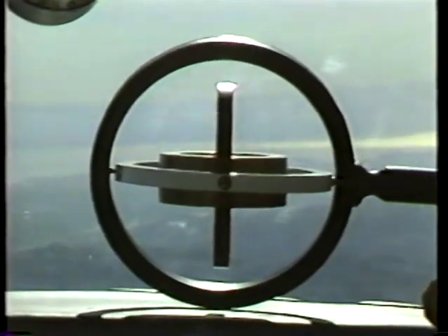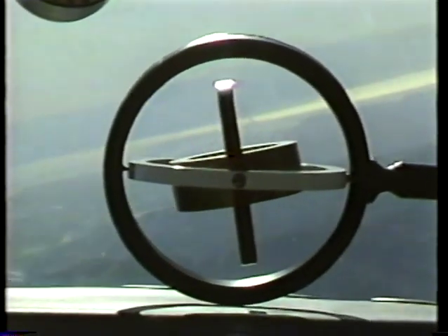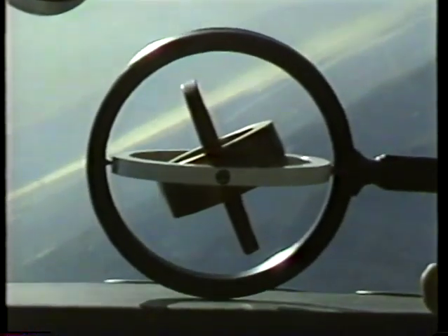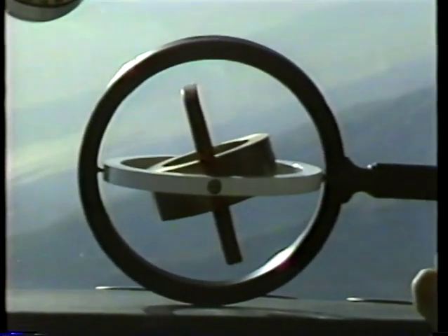It is these gimbals or mountings that allow the spinning mass to exhibit the two fundamental gyroscopic properties, rigidity in space and precession. Rigidity in space is the resistance of the spinning mass to being moved or displaced from its plane of motion. Once set in motion, the gyro tends to maintain its orientation in space regardless of the movement of its base or point of attachment to a moving object. Mounting the gyroscope in gimbals that can be attached to a base such as an airplane allows the gyroscope to remain rigid in space as the airplane moves around it.